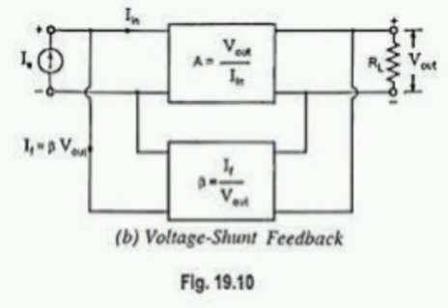When the transistor goes into saturation, VCE equal to 0. AC cutoff voltage VCE cut equal to VCEQ plus ICQ rc. AC output compliance of a CE amplifier PP equal to minimum of 2 into ICQ rc, 2 VCEQ. AC output compliance is the maximum unclipped peak to peak AC voltage that an amplifier can produce.